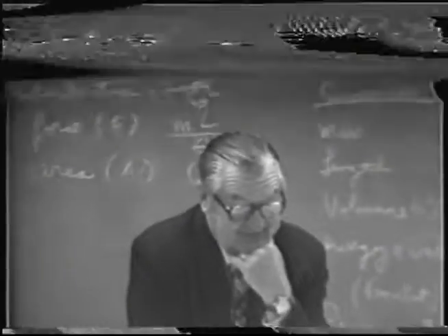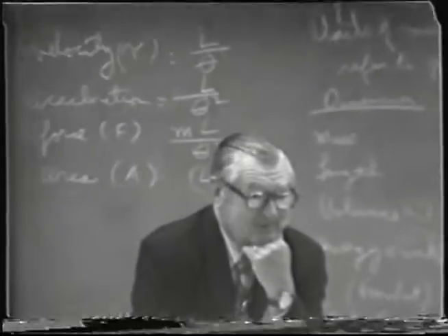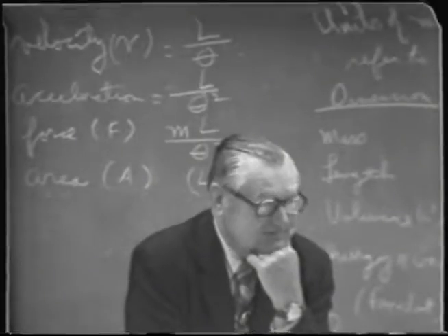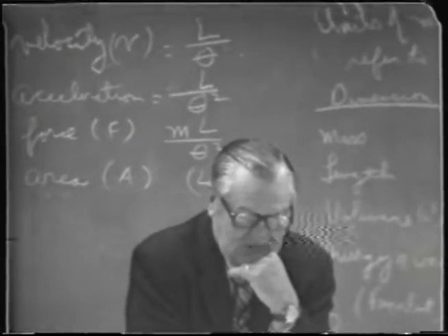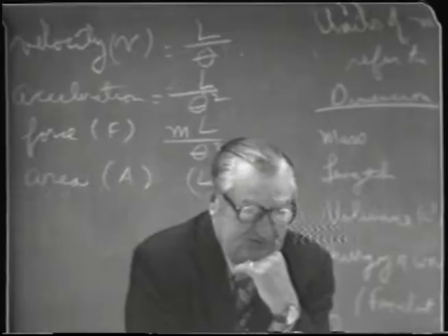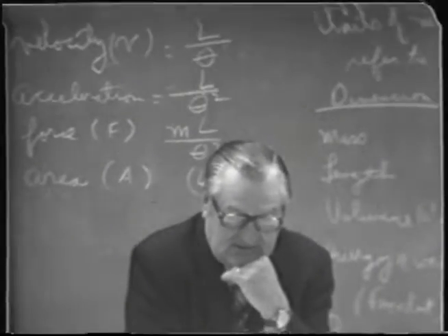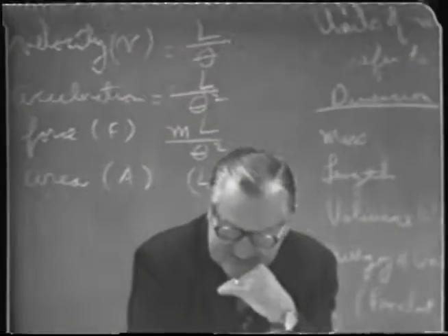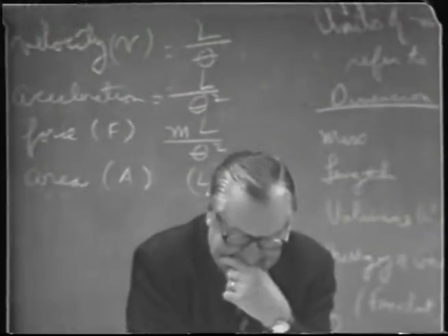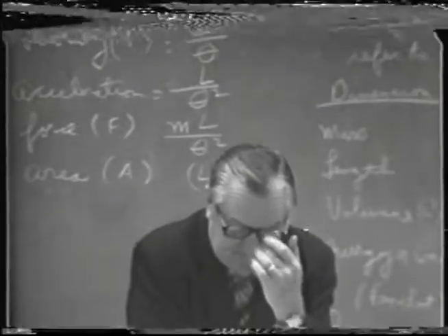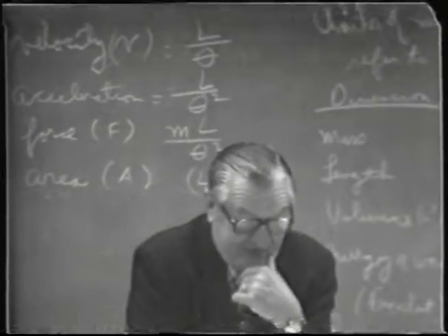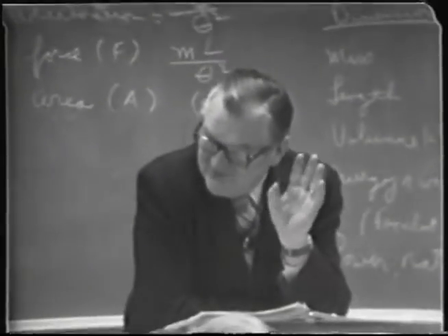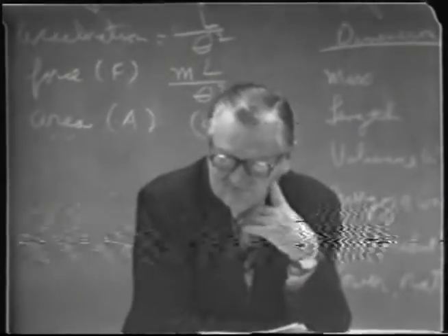Generally speaking, what you'd get from a chemist in the laboratory would be given in the metric system, CGS system, grams or milligrams per unit volume, volume percent, or grams per 100 milliliters or something. And then you go out in the plant and they want to know how many pounds per 1,000 gallons is that. So you immediately have to be able to convert it.